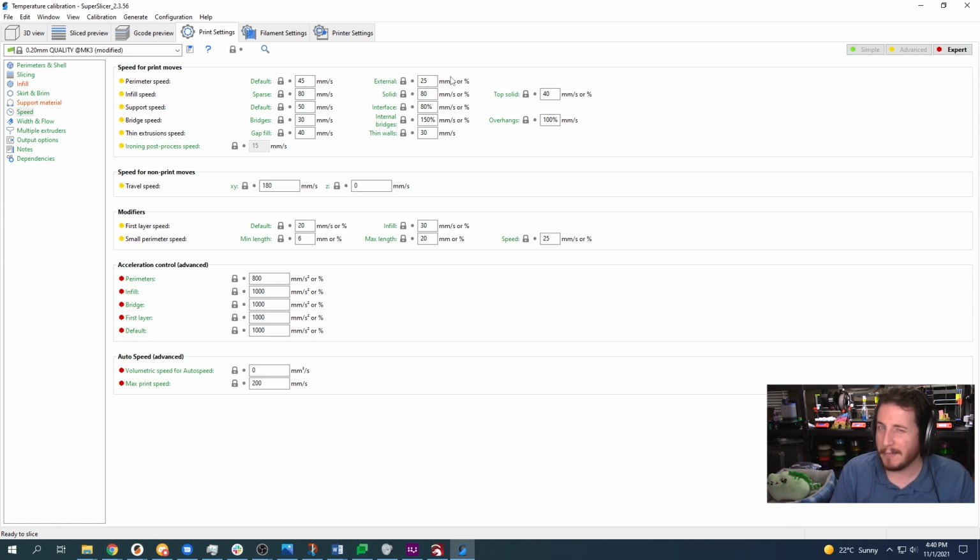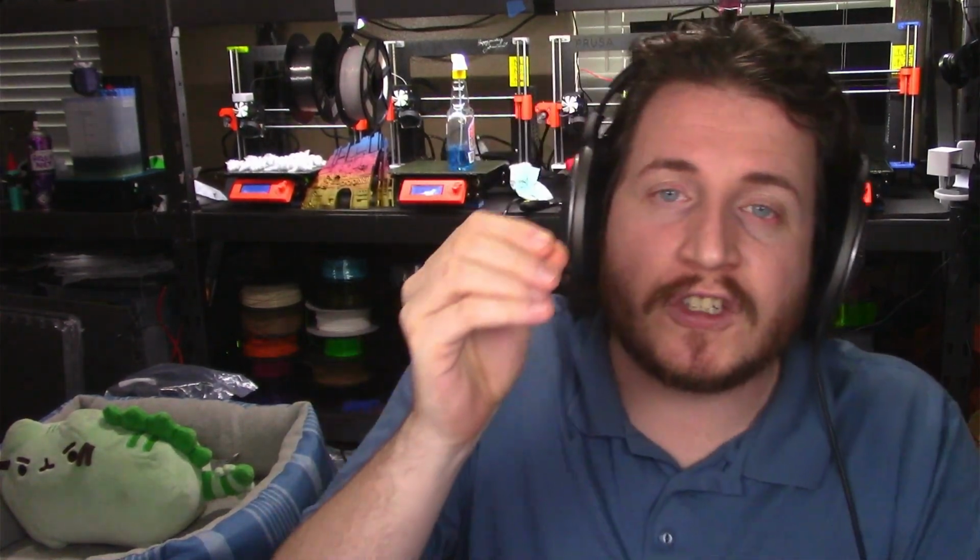I prefer that more. That way you don't end up putting the wrong thing in the wrong area, if that makes sense. Now, from what I see, we're not getting the option for that small perimeter range, and that is pretty useful when you're dealing with very fine detail components to slow down that move so that it gives the printer enough time to do the extrusion and enough time to actually slow down and cool everything off.